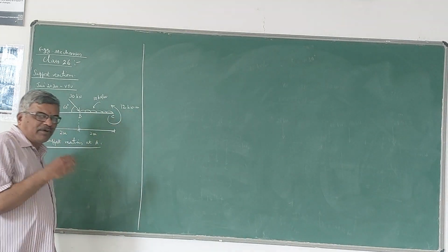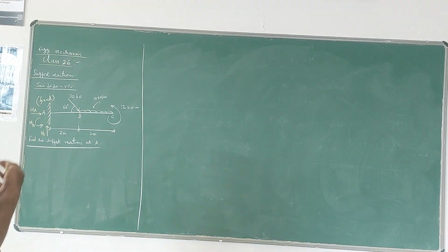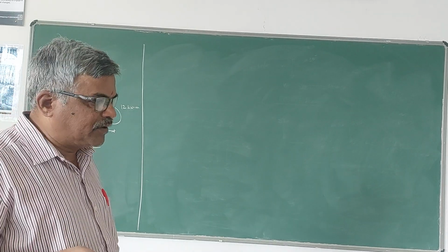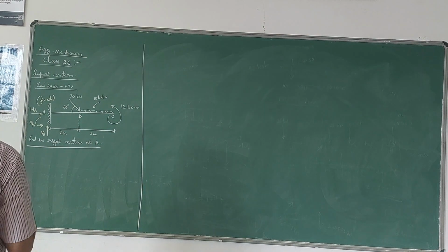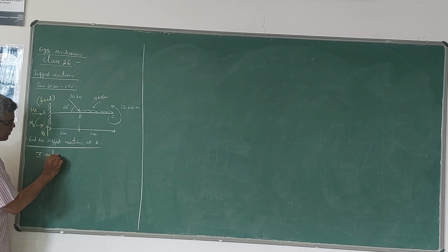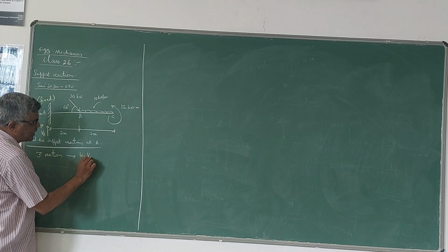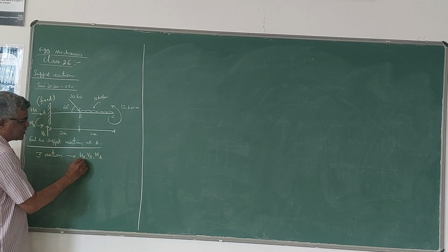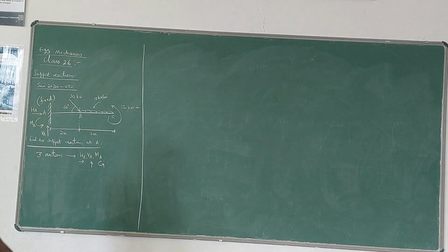Of course, the effect of that 12 kN remains the same whether it acts at C, B, or A, at any point, because as you know from the characteristics of a couple, its effect remains the same through any point in the plane. Now you have three reactions in general at the support A, and no reaction at B. So HA, VA, MA are the three reactions. Let me take HA like this, VA like this, and MA like this. You can assume any direction initially.